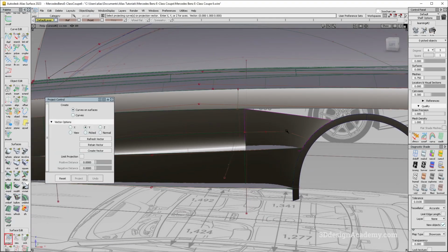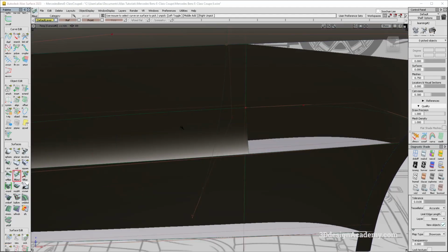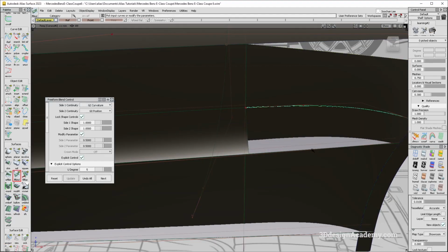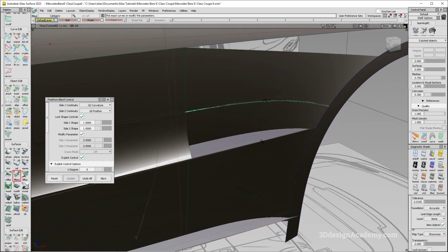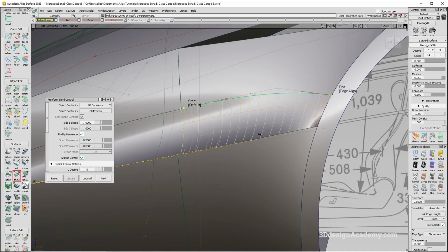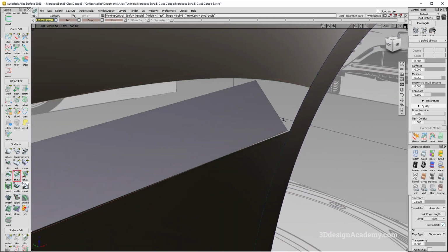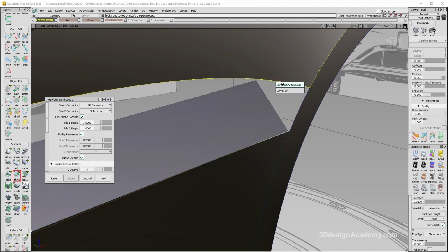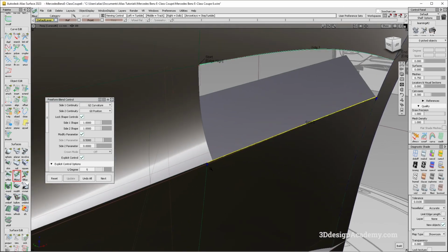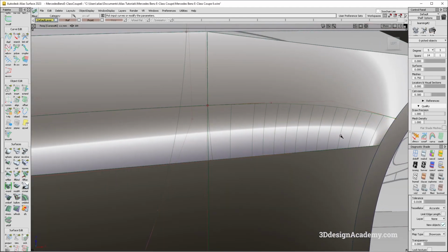And let's go ahead and project from the side. And again, I'm going to grab freeform blend. It's going to be curvature on top, and it's going to be positioned here on the bottom. It's not going to be edge line over here. It's just going to be default. Oh, okay, so wrong spot. So what I'm going to do is I'm just going to hit this one over here, and I'm going to hit this surface over here like this. Okay, so that looks a little bit better.